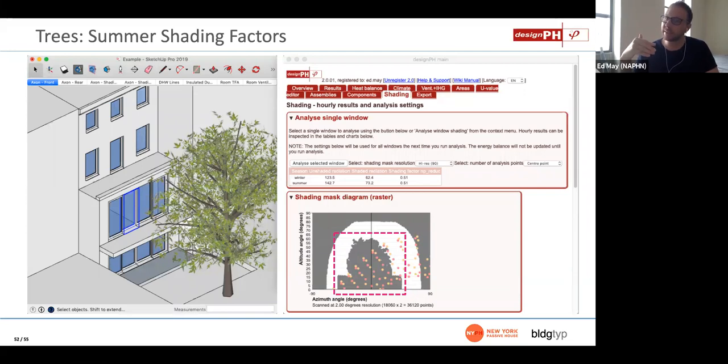And if not building heights, then number of levels, and you can just do a 10-foot per level assessment. So you can get building footprints as polylines, as well as metadata for each property, using that OSM file extract. And that's all freely available through OpenStreetMap. We do that for most of our projects. It's a very accurate way to do that, for sure.